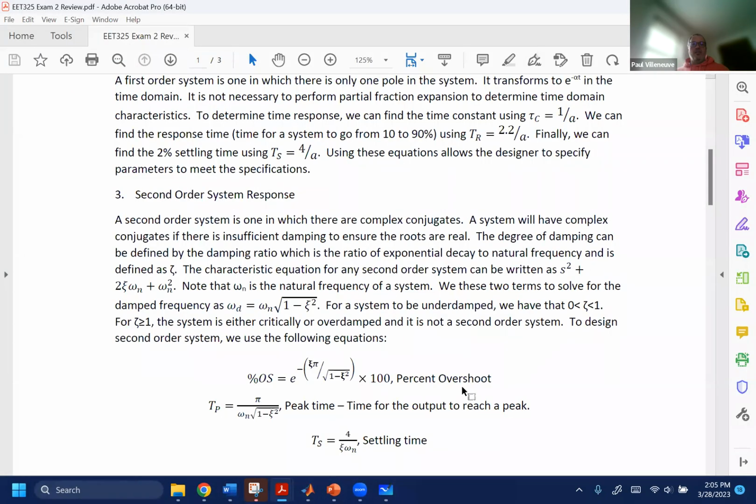Okay, hopefully you can still see the sheet that we're working at, which shows the second order system response. And the second order system response, we did a lot of work on that. And we looked at the different system types, mainly as it relates to the type of damping or how damped the system is. We looked at three cases where we had an overdamped, a critically damped, and an underdamped. And the underdamped case considered that there was no damping whatsoever. That's still considered underdamped.